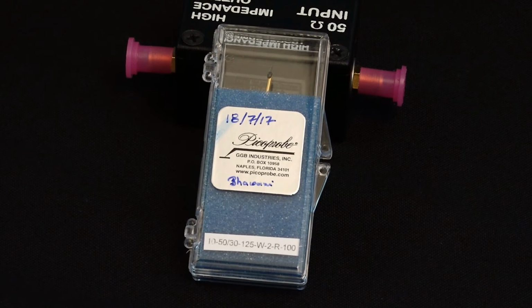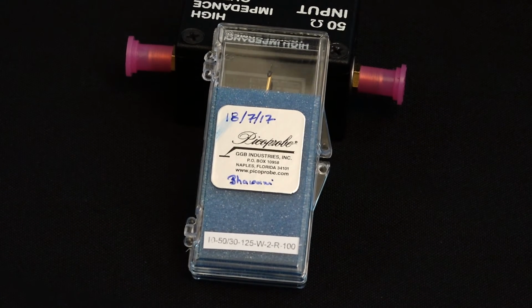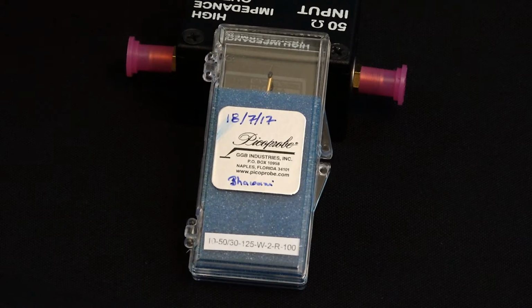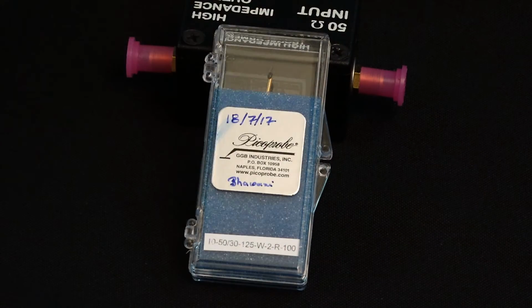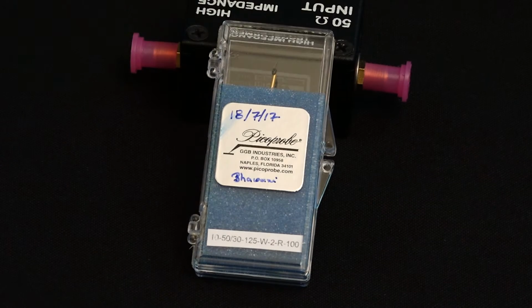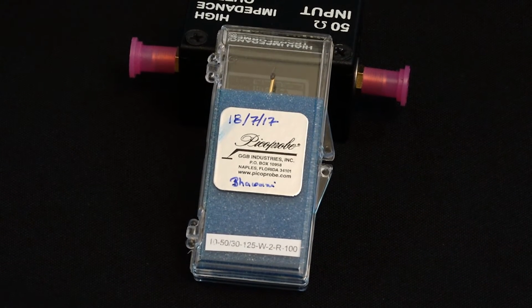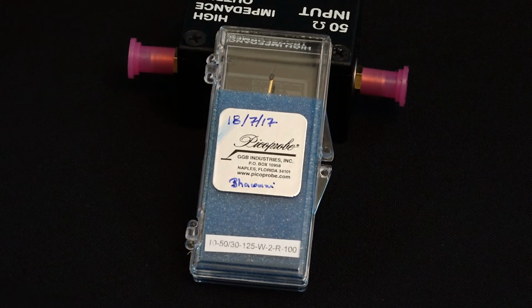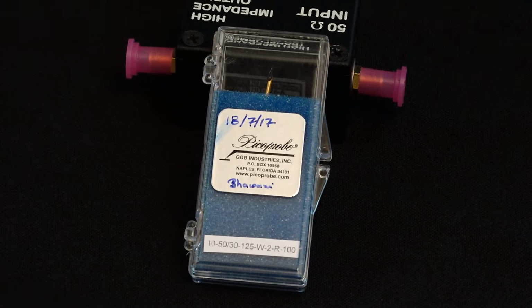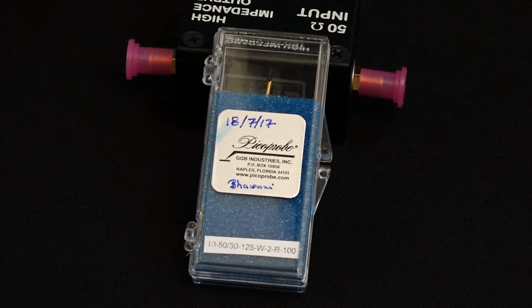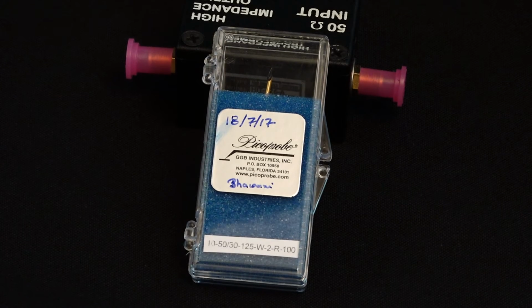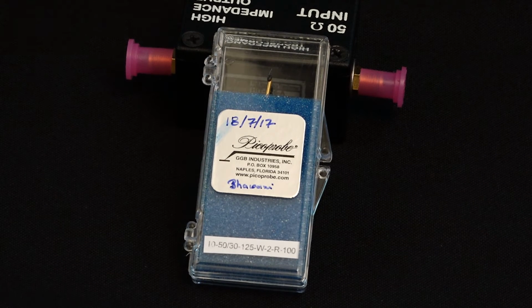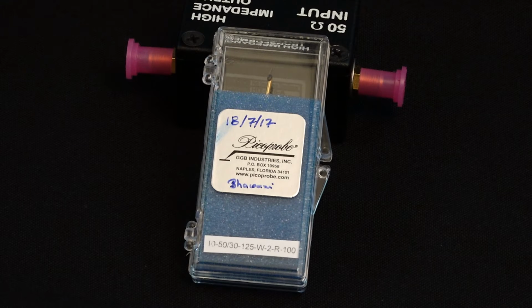Finally, the 100 here is the pitch of the probe tip. What is the pitch? These two probe wires have a certain distance between them, and this distance is 100 microns. So you cannot measure devices where the contact pads are less than 100 microns apart. For example, if I were to fabricate a 2D material device where the contact pads are far apart only by 50 micron, you would not be able to measure those devices through this probe tip.